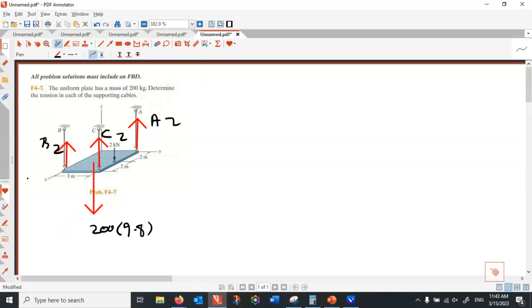That's the free body diagram. You don't expect any reaction in y direction or x direction. You don't expect any bending moment because none of the support can take the rotation, can resist against the rotation.